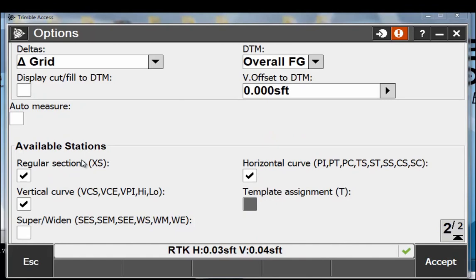A little nuance to know, we spent a few hours digging into this. If you have a corridor model that's 10-foot frequency, say, and you try to stake in between that, in a corridor model you wouldn't necessarily want to cut a cross-section between two assembly insertions. So if you model that at 10-foot intervals and then you stake that to plus 25, you're going to land in between. And what's calculated there, as best we could tell, the Trimble software is not taking the exact strings as I've defined, or the feature lines as I've defined in the corridor in Civil 3D. It's recalculating that based on target objects and everything. It's pretty intelligent as we found. So it's not just like an export of all those 3D lines and then you just stake along those lines. It's a little smarter than that.